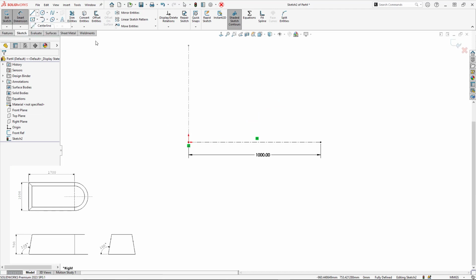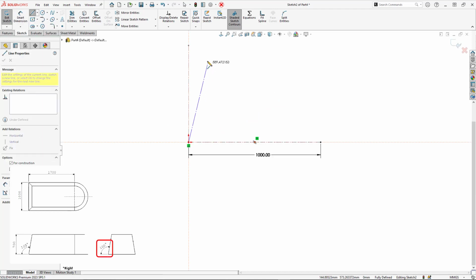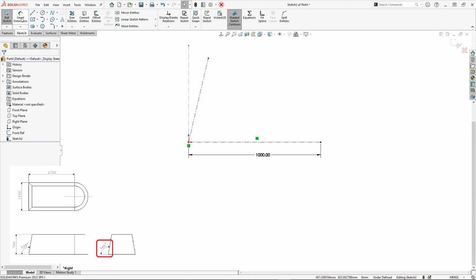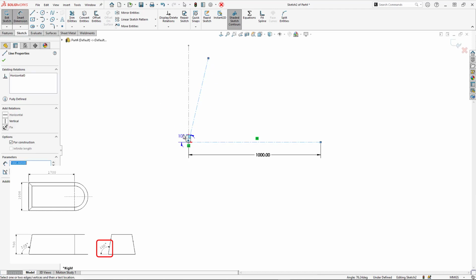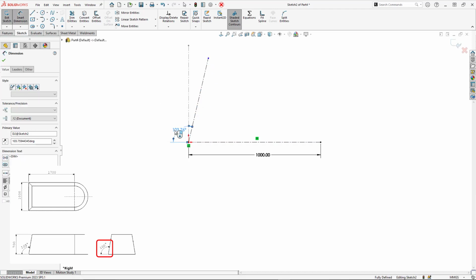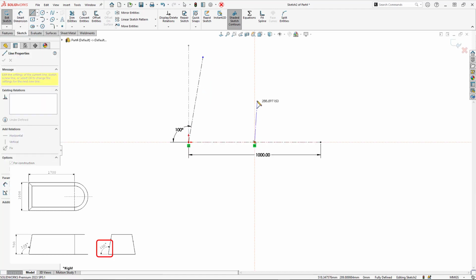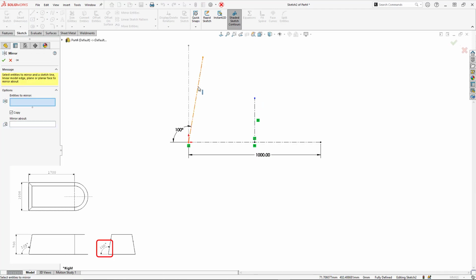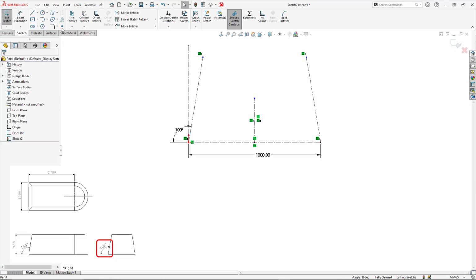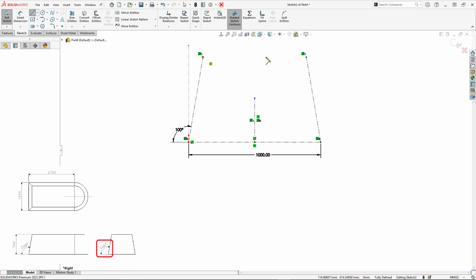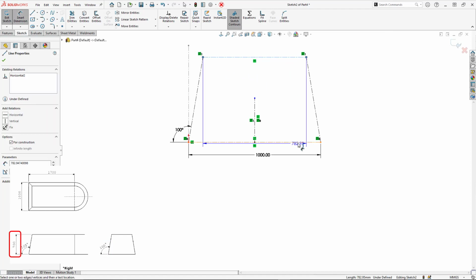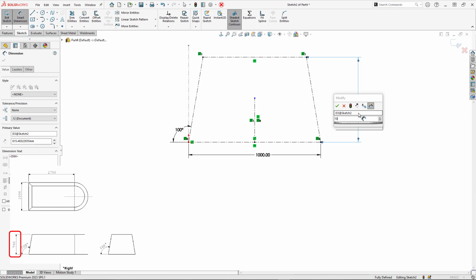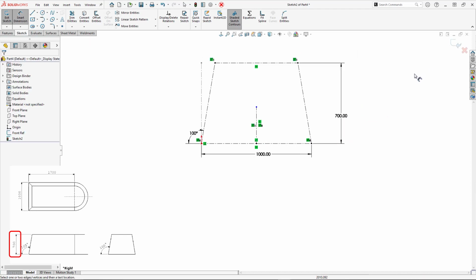Once you have that initial line, we can snap this into a normal orientation. Again, I'm directly on the right plane, so I know that my sketch angles are going to be exactly as they're specified in the drawing, which were in those orthogonal views. I'm just saving myself some time. I'm going to actually mirror this left line over to the other side. They are going to be symmetrical, and we'll close this up as well. So it's going to make sure that the line on the right portion is the same as the left, and it's going to have that 100-degree angle.